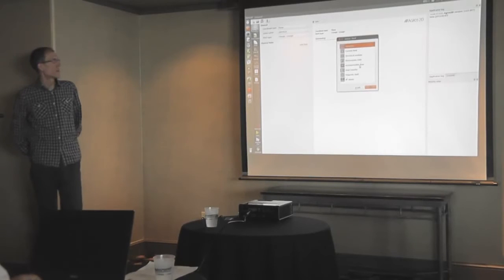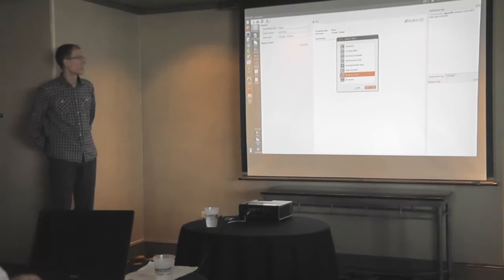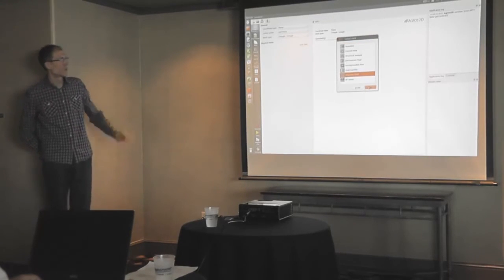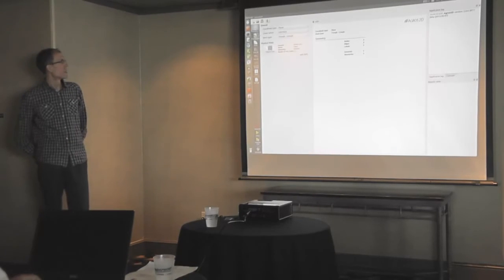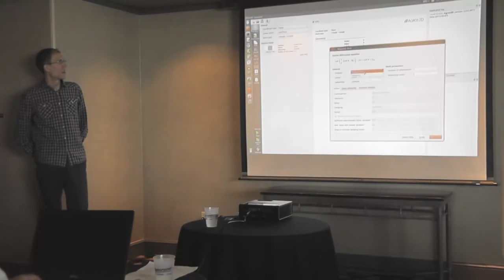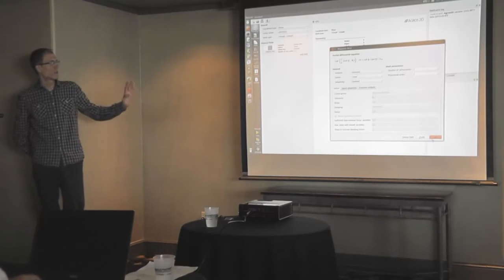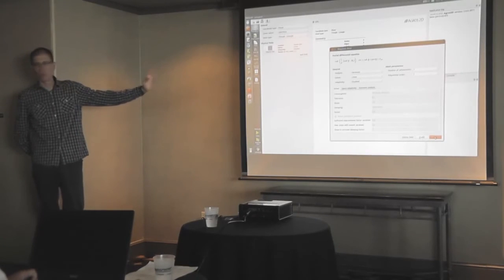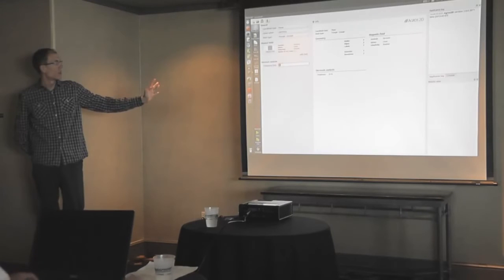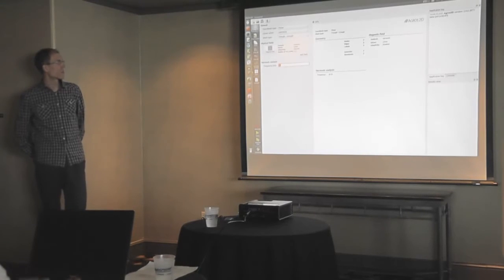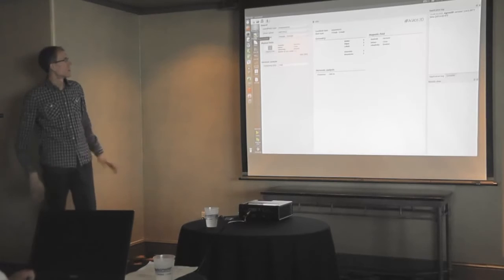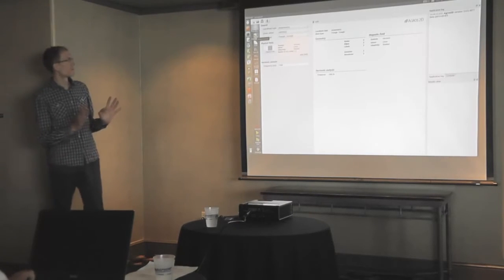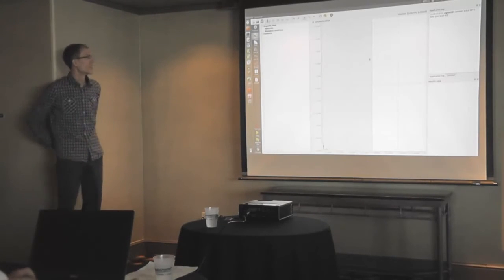So we start with selecting the field we want to use, which is magnetic field. And we select basic properties. We want to use harmonic analysis. Okay, we select the frequency. Proceed to, we use axisymmetric calculation.